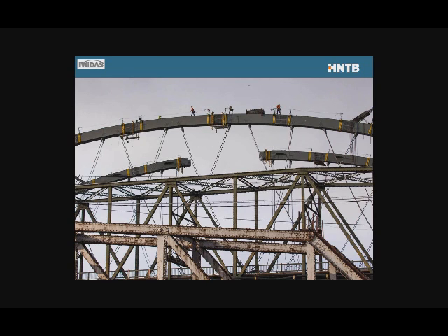You can see this is the Amelia Earhart Memorial Bridge. Disregard the junk in the front. These are the older bridges, and what you see is the ribs of the new arch bridge in the background. You can see the cables are about to be installed. These are, I think, like 2.5-inch diameter bridge strand or wire rope, and in pairs.